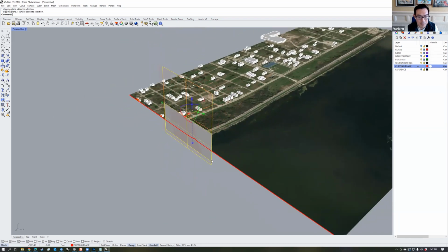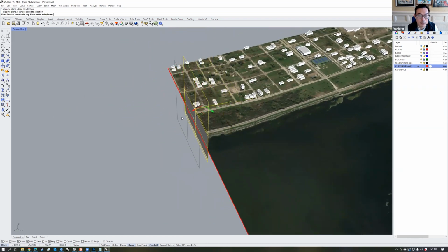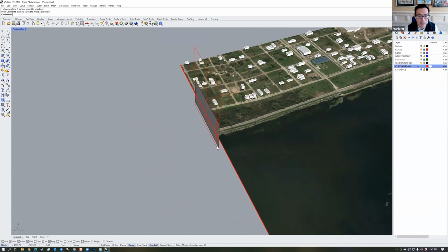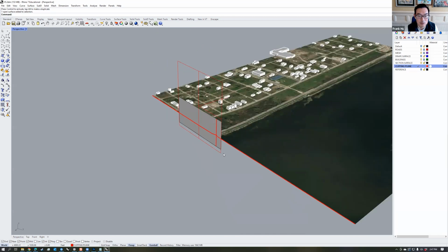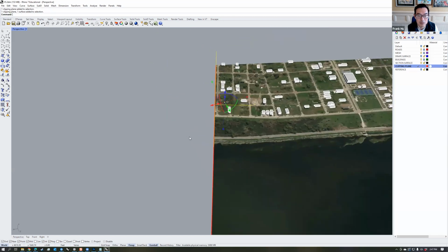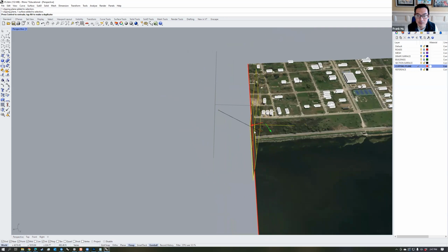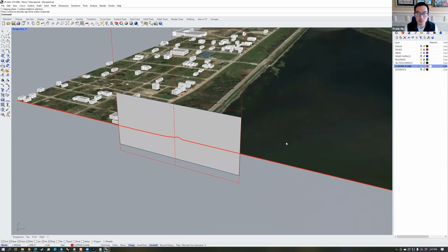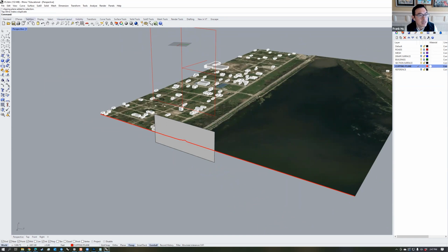Now, this clipping plane, if you move it around, cuts through the model wherever it's located. We want that clipping plane and that surface to be coplanar for one very specific reason. So let's move it to some location. Eventually, you'll pick an area to cut. Let's say the area we were at right here. You can use a tool in the Set View tab called Look at Surface. So I choose Look at Surface, then choose that surface. I have to choose a corner of it, and then pick somewhere on that surface.